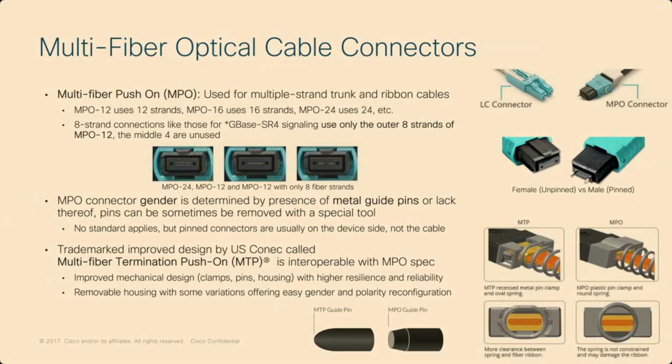There's no official standard on that, so when you buy these cables, in many cases there are ways of removing the pins or adding pins if needed. There's just a little cage in the back that has a spring-loaded mechanism that locks down those pins, and there are little tools that you can use to pull the pins out.